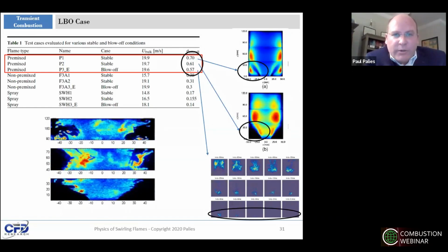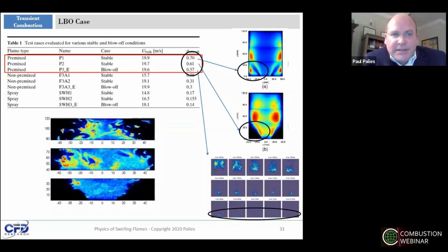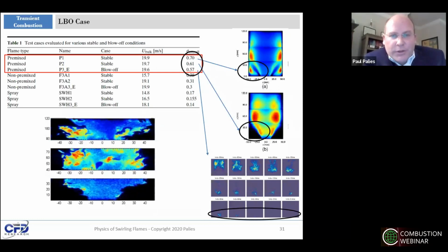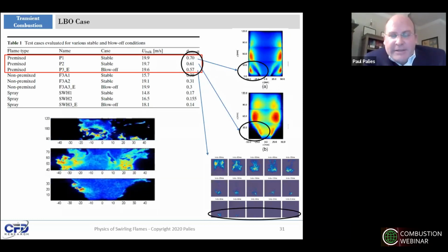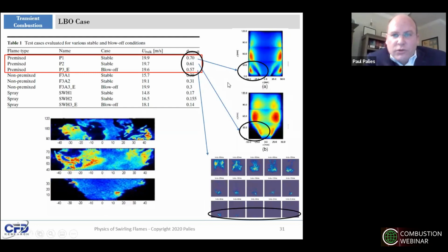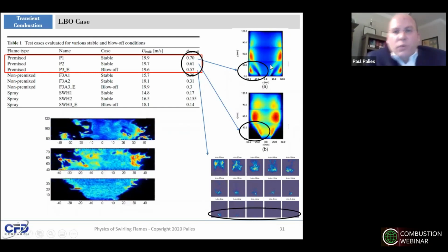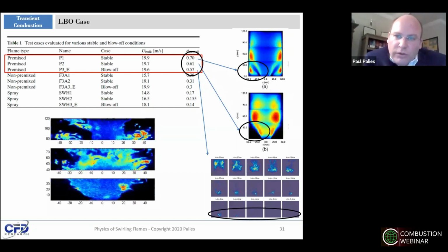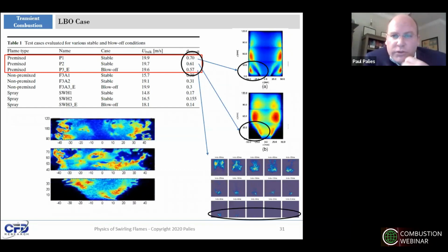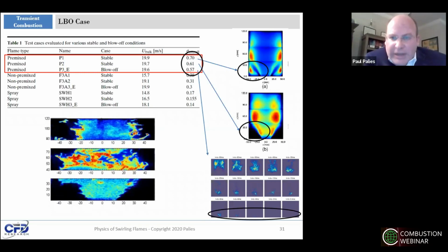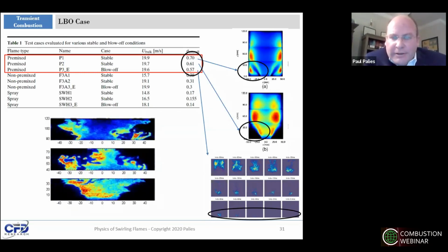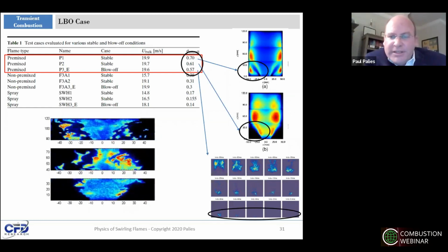There were three points experimentally investigated: 0.7 equivalence ratio, 0.61, and 0.57. The 0.7 and 0.61 cases were interrogated with OH PLIF, and the 0.7 equivalence ratio shows some reaction, OH star, in the corner recirculation zone, while the 0.61 did not.